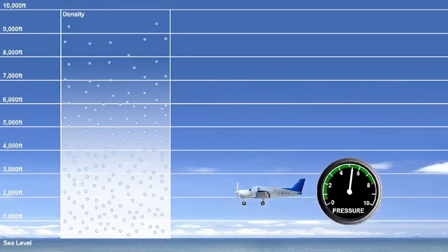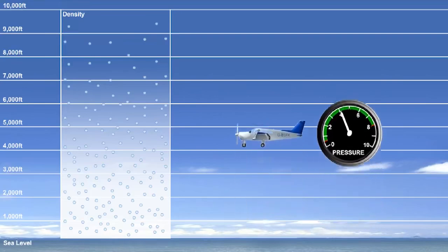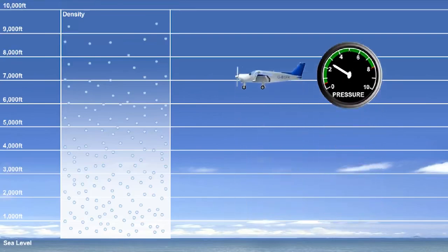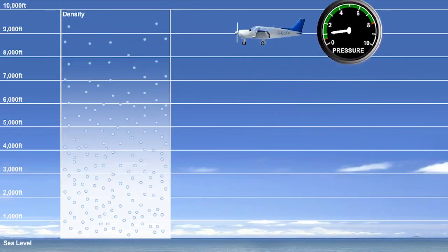This, coupled with the fact that the pressure available in the atmosphere to assist the flow of mixture into the engine cylinders is reducing in the climb, means that less and less weight of fuel is fed into a normally aspirated engine as the aircraft gains altitude.